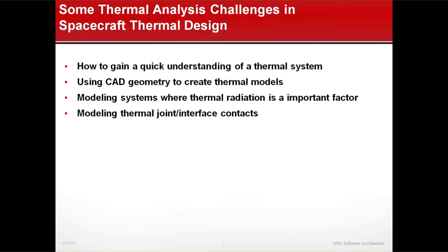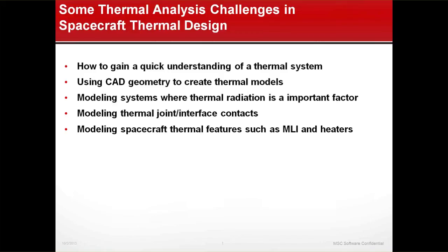Modeling joints and interfaces is critical in thermal design of spacecraft. You may have a bolted joint that works very well on Earth, but when you get up into the vacuum of space, those connections can just disappear. Even though it's a good structural joint, it may not be a good thermal joint. I've seen some big changes on electronic equipment and boxes that may work at room temperature, but then certain devices will fail because they no longer have convection, for example.